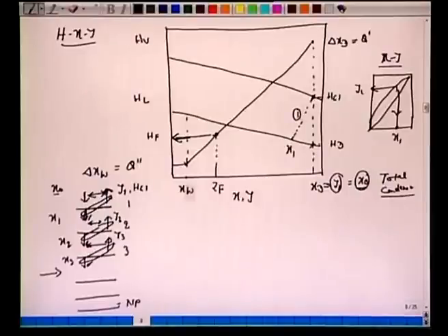So the stage starts from here, first stage. Now we know this difference point. We can connect this X1 to this difference point. Essentially, knowing this X1, we can find this X2. That's the operating line. So if this X1, this is Y1, we obtain this Y2 or HG2. All right, so this is the way we are moving. Y1, Y2. We have X0, we have X1.